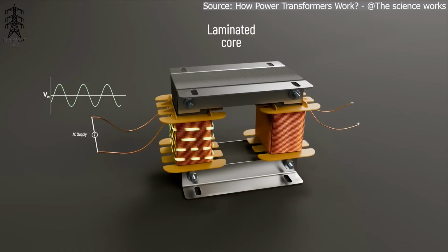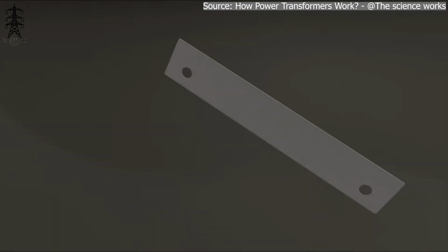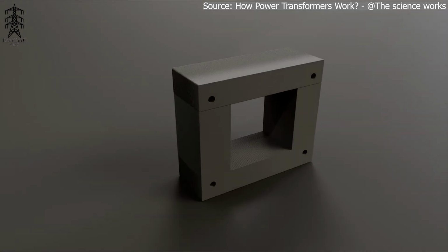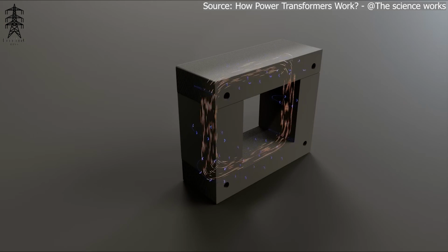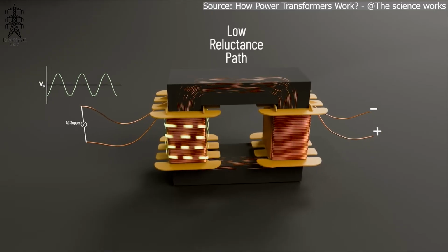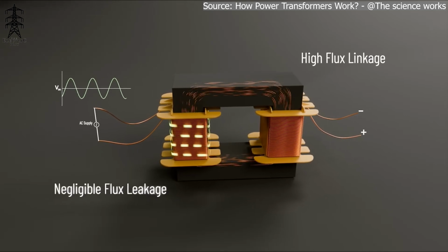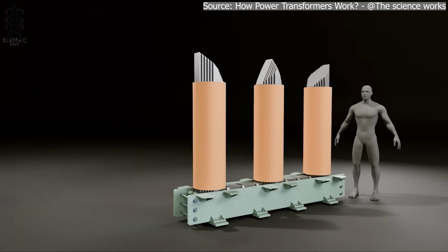In addition to windings, transformers also have a core made from silicon steel, which is steel made in laminated layers with insulation placed between each sheet, which helps to minimize energy loss and improve efficiency by reducing eddy currents, which are circulating currents within the transformer. The core itself helps channel the magnetic flux created by the transformer windings, further reducing losses. We'll have a future, more in-depth video on transformer theory, but for now we know what a winding and a core is.